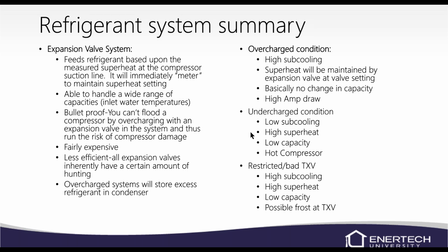In an undercharged condition, we have low subcooling, high superheat, low capacity, and your compressor will be hot. Restricted or bad, it really depends where it's restricted. I have seen a few times where the valve gets stuck mid-position, and so it may work fine for a while, and then when it needs to start adjusting, that's when we run into our problem. So restricted, we're going to have high subcooling, high superheat, low capacity, and possible frost on the TXV.